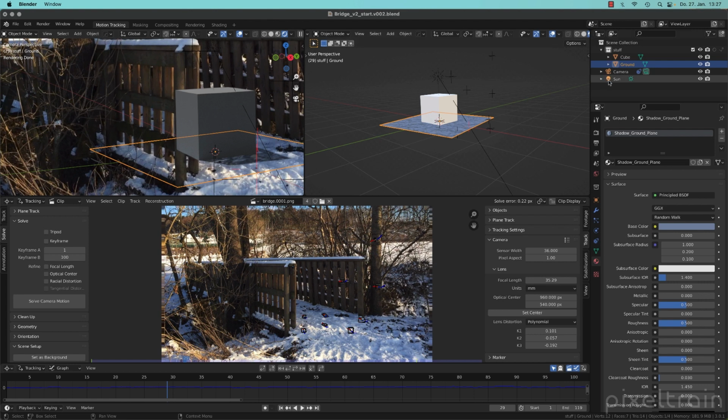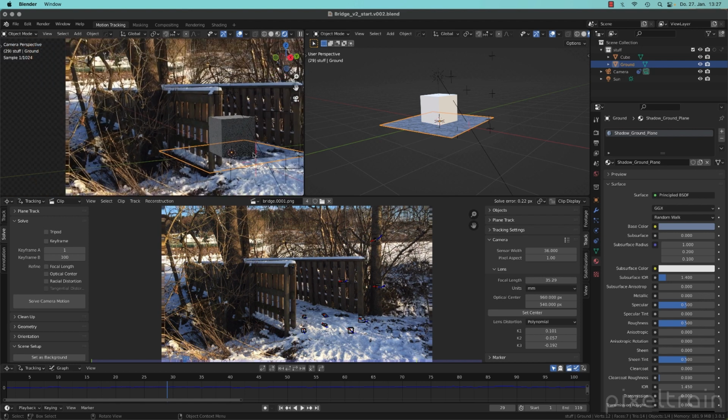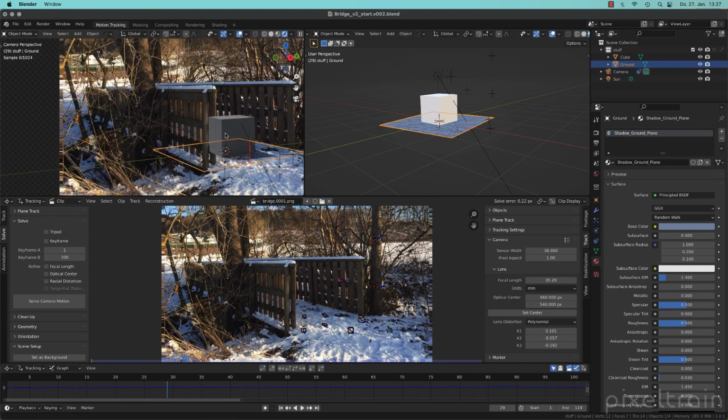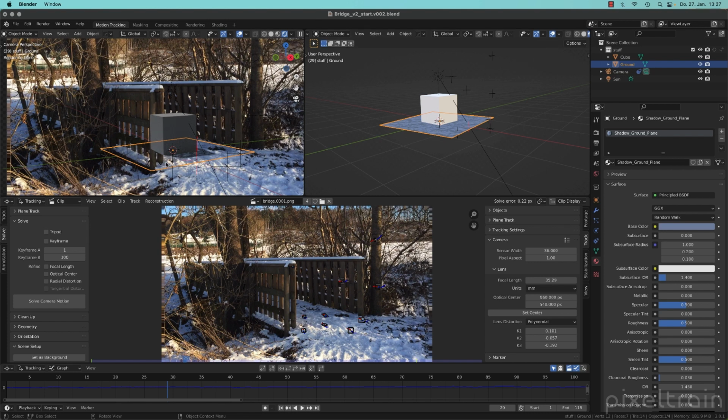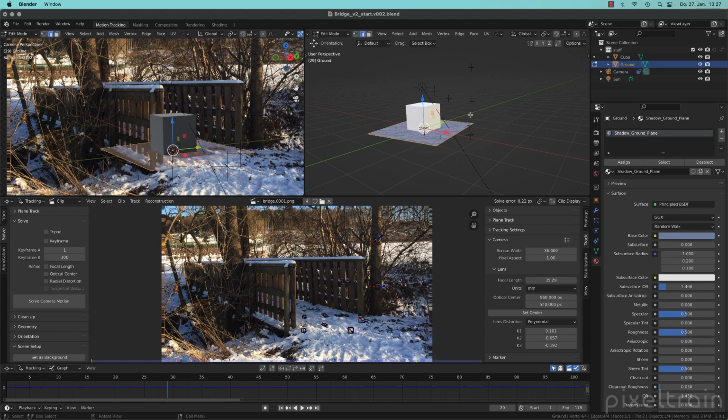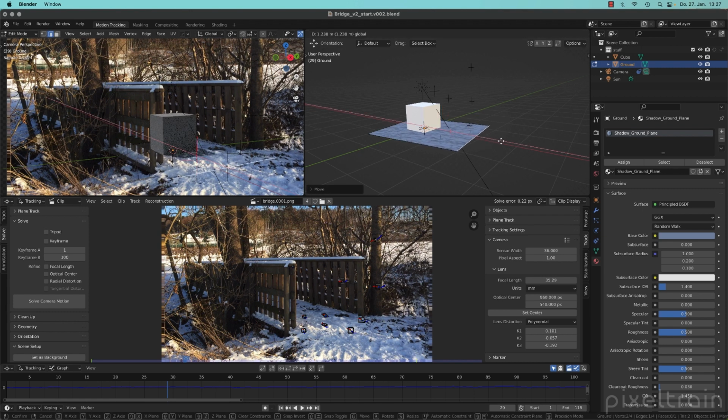And now you normally go in after you've found the right reflections, the materials and so on, and make a nice light integration, which I don't do at the moment because this was a demonstration of how to do that. Another thing, this Shadowcatcher is only catching the shadows in the area where the Shadowcatcher is. That means if you have a Shadowcatcher which suddenly is too short, you will run into problems. So if you go here now and I select this edge, you see the Shadowcatcher only calculates to this part.